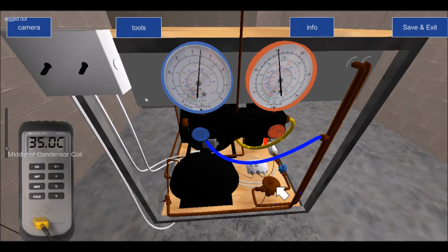The problem with relying on an expansion valve nowadays is that there are so many retrofit gases on the market to replace the old refrigerants that are being slowly phased out. R22, for example, was phased out in 2010. 404A will be phased out by 2020. And so on, but there are drop-in gases coming in all the time. So you might find a 22 valve sitting on your system, but the gas in it is 407C or something equivalent, 407C being a drop-in gas. So it's not as reliable as it used to be.